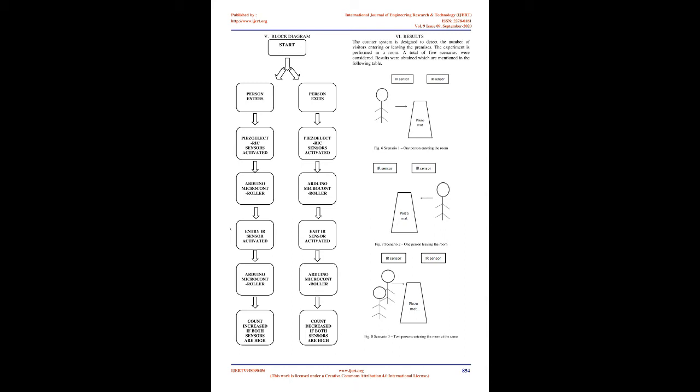The board consists of other components such as serial communication, crystal oscillator, voltage regulator etc. It consists of 2 KB of RAM, 1 KB of ROM, flash memory of 32 KB and can be easily programmed with the open-source software Arduino IDE. It also includes 14 digital I/O pins for both reading and writing data, and 6 analog pins for reading input.